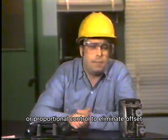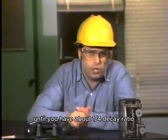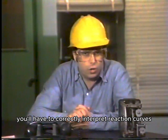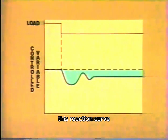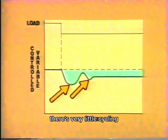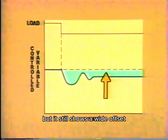To eliminate offset, you adjust the gain until you have about a quarter decay ratio. Then you increase reset until the offset is gone. To do this, you'll have to correctly interpret reaction curves. For example, this reaction curve shows less offset than the one we just saw, but it doesn't have a quarter decay ratio. There's very little cycling, but it still shows a wide offset.